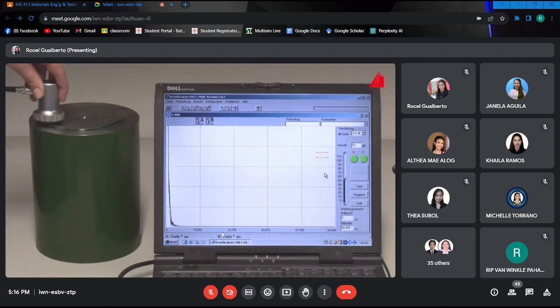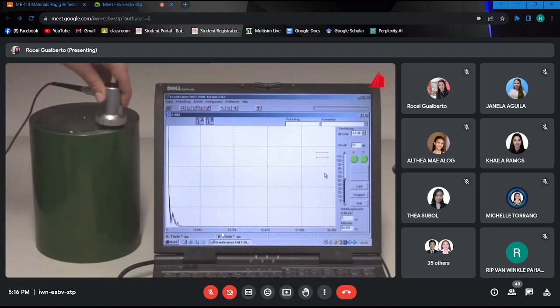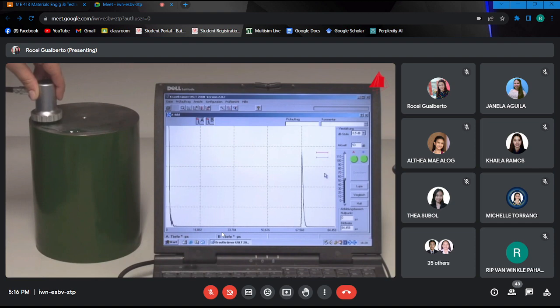The material tester spreads out the gel evenly on the top surface. That way she is able to examine the entire cylinder. Using the velocity of sound in the material, one can plot the calculated depth on the monitor to the right instead of time. A very useful feature.